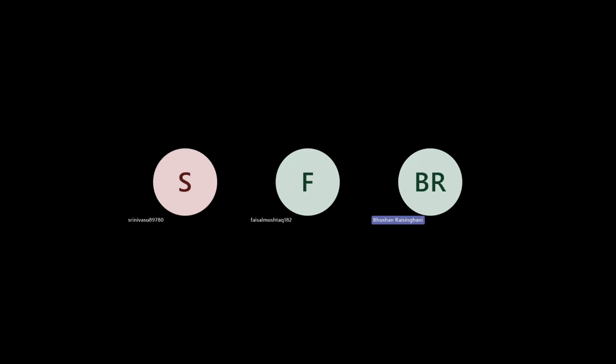And wherever the difficulty is there, you can put it like, I have taken a problem and I am facing this difficulty. I have uploaded a problem also in MS Teams for an 8-story building. You can break it into 3-story also and solve it manually, and also solve the 8-story building manually, for the gravity case and also for the lateral case. There is a simple mass to be estimated, stiffness to be estimated. In the static method, you have to multiply by VP into AH. You will get the base shear, then the distribution along the height. That is the analysis you have to do for that particular case.